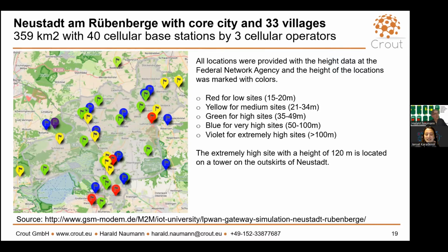With narrowband IoT we have time synchronization. That means if the time synchronization is not working, then we may have a signal, but maybe no communication. That is the difference to LoRa, because it's non-synchronized. Officially in Australia, the narrowband IoT range was, I think, 100 kilometers guaranteed by the operator, but they tweaked the base station a little bit, so they had to change some settings.